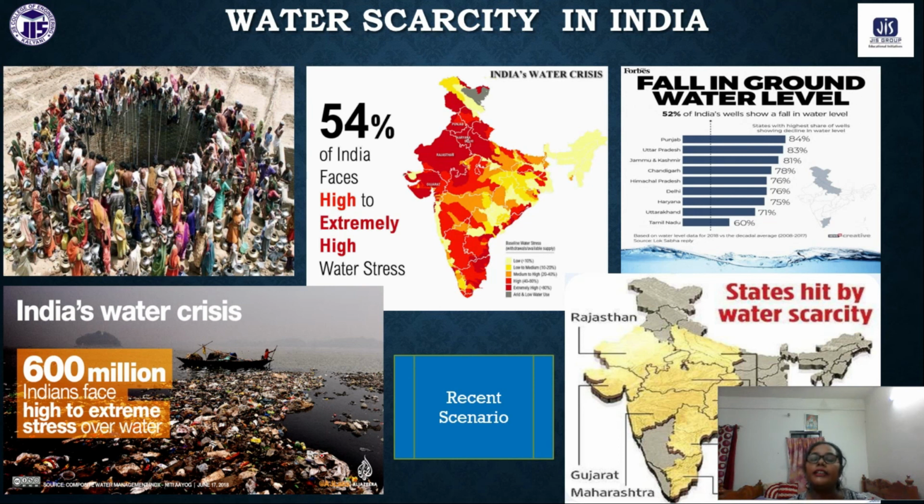After that it dissociates into HCl and nascent oxygen. This nascent oxygen is very important to kill the germs. For ozone treatment also, ozone dissociates into oxygen and nascent oxygen, and that nascent oxygen can kill the germs. So this is all about the primary treatment and the disinfection procedure.